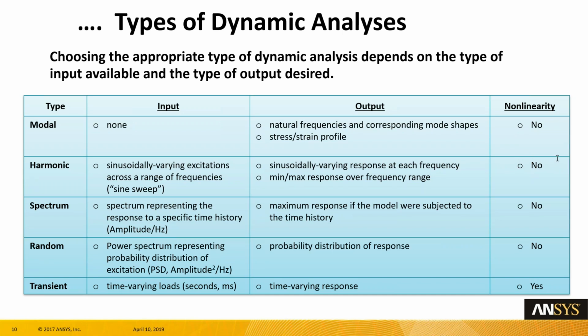For transient analysis, does damping ratio have to be mass or stiffness damping? For transient analysis, we can specify either a mass damping or a stiffness damping, or we can specify both. Please note that if you specify mass damping and stiffness damping, the results are cumulative, meaning that mass damping will add linearly to the stiffness damping.